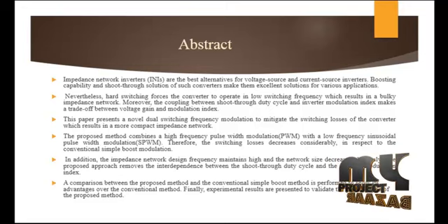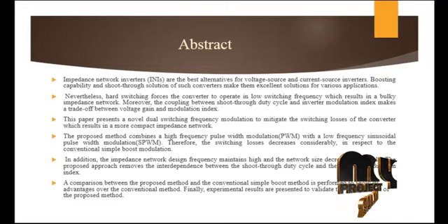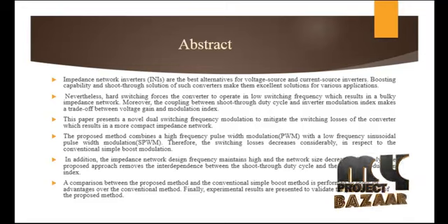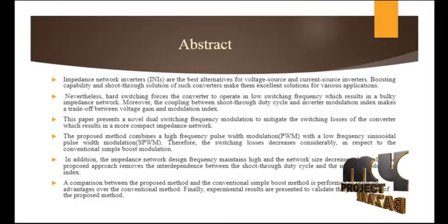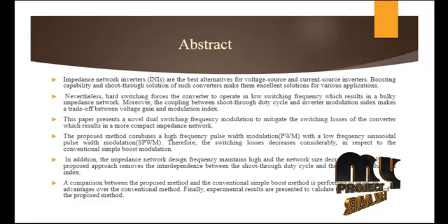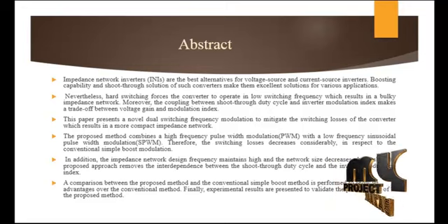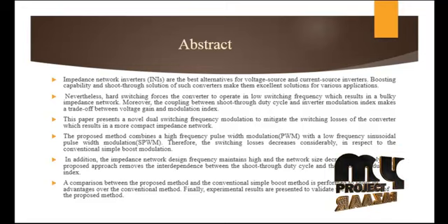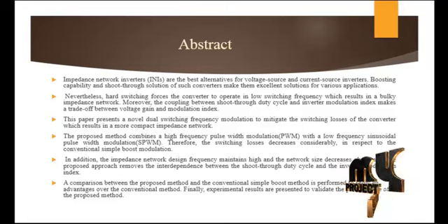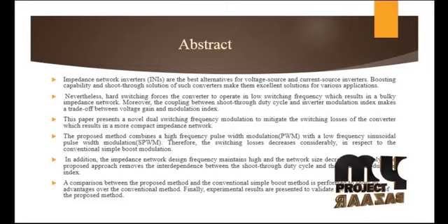The proposed converter also removes the interdependence between the shoot-through duty cycle and the inverter modulation index. A comparison between the proposed method and the conventional simple boost method is performed to show the advantages over the conventional method.